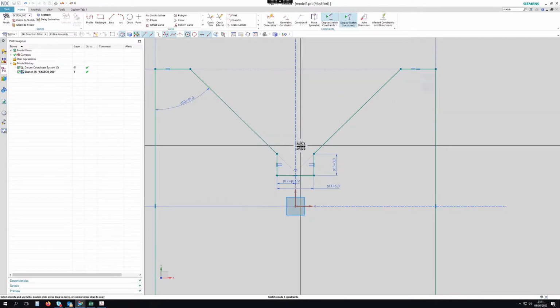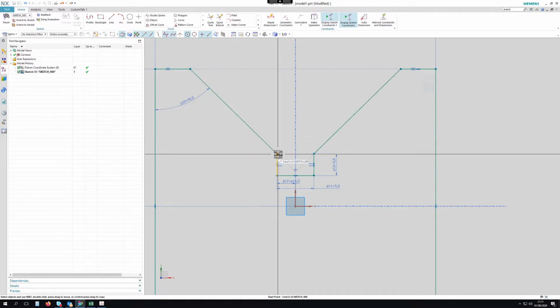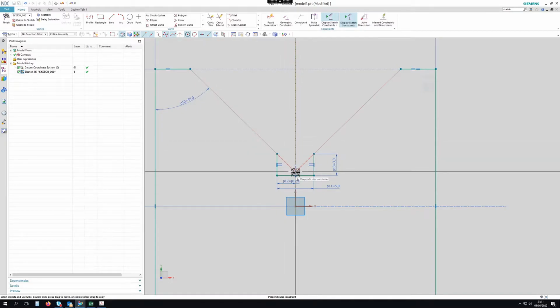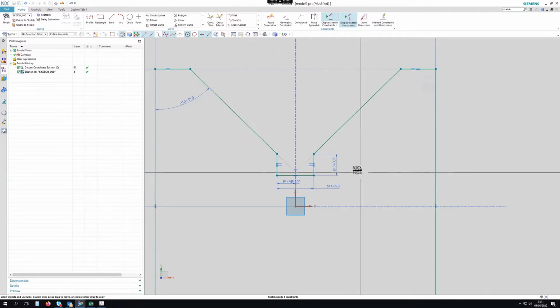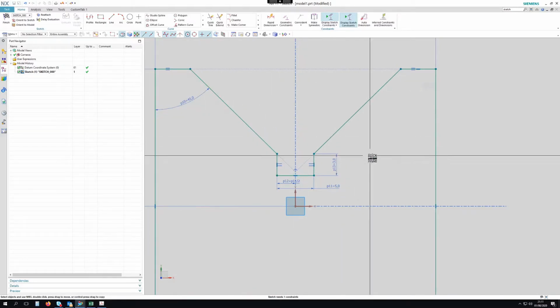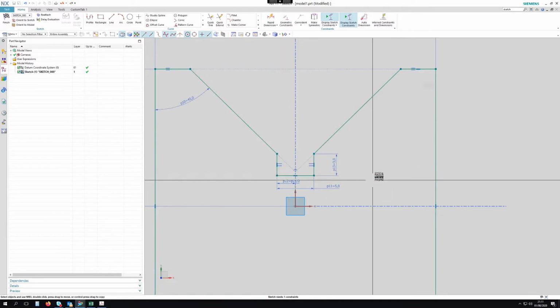Basically what I'm after here is a V-block, usually used to hold a round bar for drilling a round bar or similar, and I want to make sure the very bottom of the V is slightly higher than the undercut, so I've got a little bit of clearance here. And 3mm looks about right. I'm going to try and change the sizes and see how that affects where that point is.